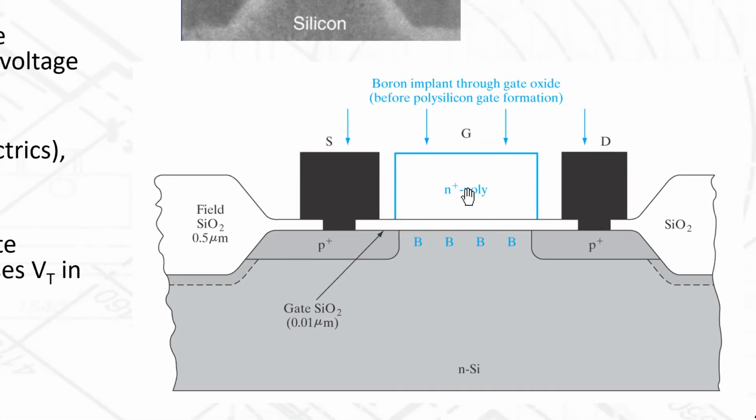Imagine that there are positive charges deposited on the gate, and then you have the negative charges on the other side of the gate. If the gate's super thin, then the positive and negative charges are close to each other, right? So it's an easier way to communicate to the other side of the gate. On the other hand, if your gate's like 10 meters thick, if you deposit positive charge on one side, there's really no hope you're going to get any kind of negative charge on the other side.